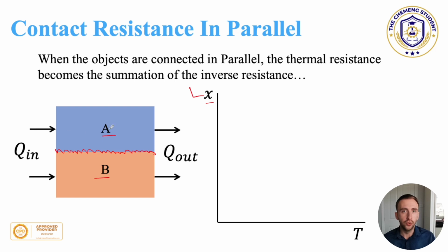So we're going to lose some amount of Q as we progress from point 1 to point 2. Now what that would look like is a change in the temperature. As we move through the distance, we will have this decrease in temperature. Now the steepness of the line is of course dependent on the thermal properties of that given material. So this is just a very generic example.